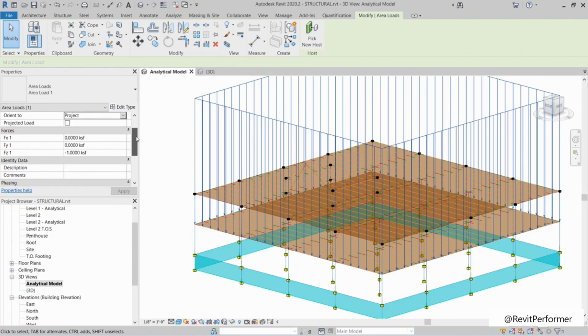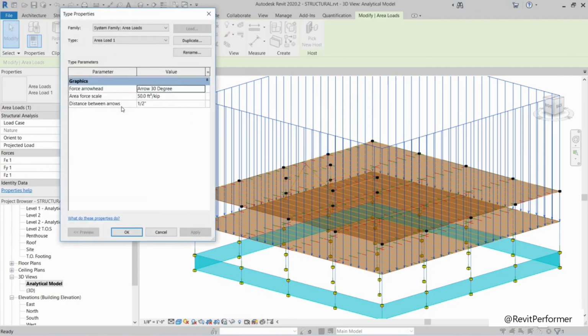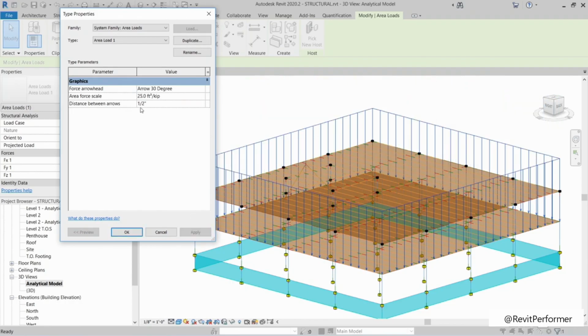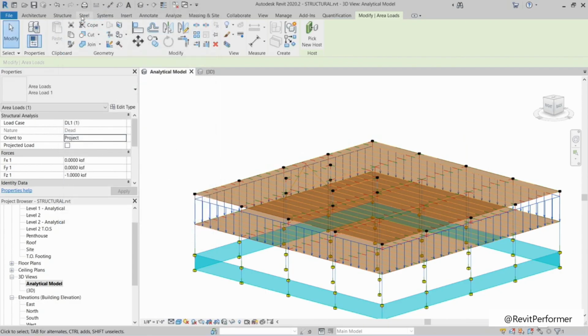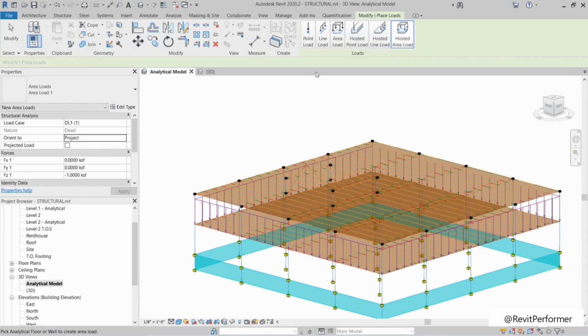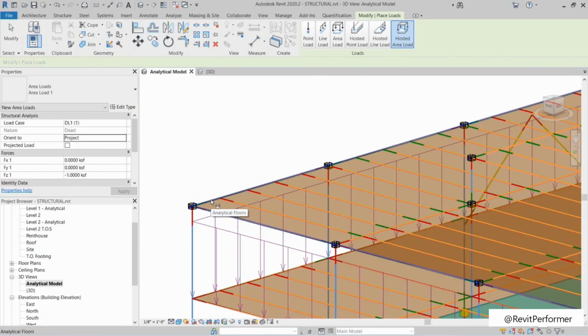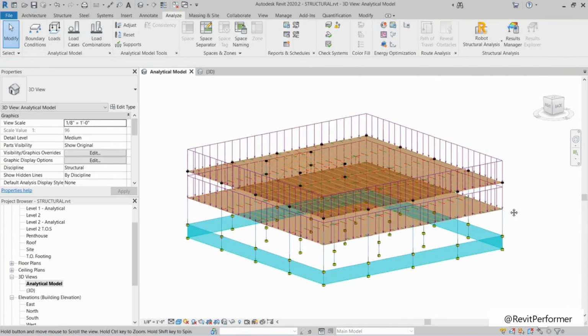Click cancel here, click cancel here, click cancel one more time, hit escape a few times, and of course we can always go to Manage, Materials. Now we can find any material we want. So if we type in conc, most of these should have their physical material selected. You can come in and change these. So when it says concrete lightweight 4 KSI, we see right here that this is 4 KSI. Let's hit cancel. There you go. It was pretty short, but now you're going to have to pay more attention to materials.